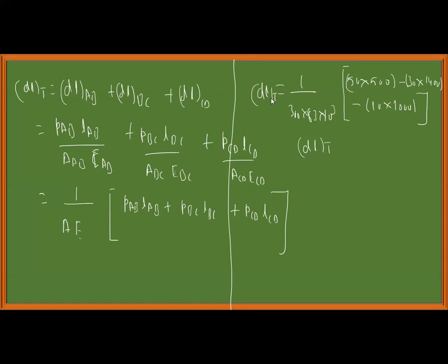1.08, sir. What is the unit? Sir, mm, sir. Yes, mm. We are calculating everything in mm: area in mm square, stress in Newton per mm square, and Young's modulus in Newton per mm square. So the deformation we get is also in mm, 1.08 mm. So the bar is under compression. Due to this combination of load, the bar is under compression, 1.08 mm compression. Okay.